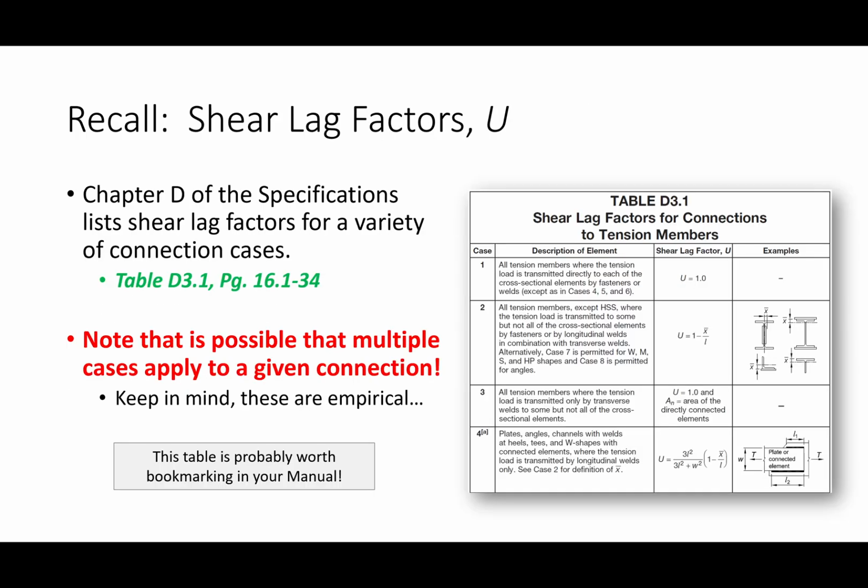Our shear lag factors, this is from the new manual, from the specification document. You just go through and assess which cases apply; multiple cases may apply. But the big one you need to ask is whether you're in case 1 or case 2. It's going to be one or the other, at least for bolted connections.